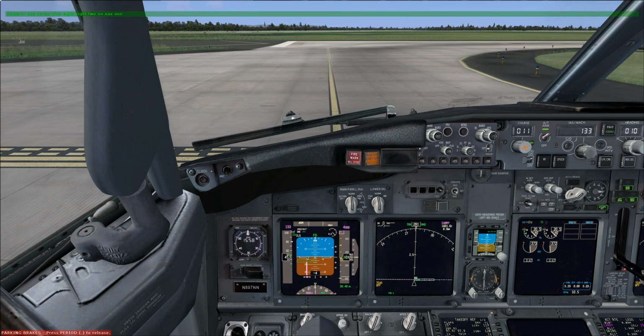If, however, it is a very strong crosswind, then you might not be able to even keep it on the runway no matter what you do, and you may go off the edge before you get airborne. Another thing to look out for is, as you get the crosswind during takeoff, let's say from the left side, that wind would get under the left wing and try to lift that wing up, and you run the risk of striking the right wing on the ground if you're not careful.